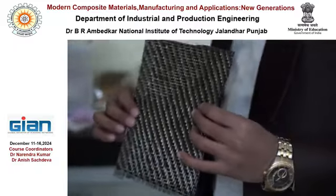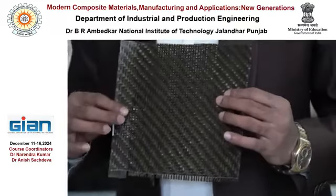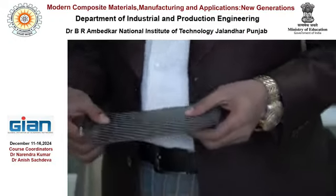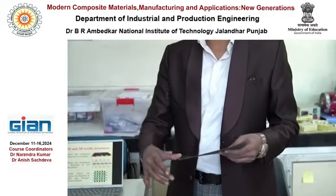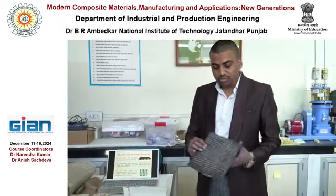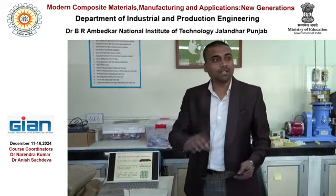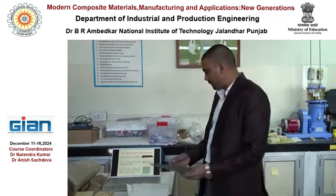In this particular case, we can see that the yarns are placed in two directions, and this fabric is two-dimensional. It has length and width dimensions only, and the thickness dimension is very minimal, so we do not consider it, and we say that this is a two-dimensional structure. We can also have the unidirectional preform, where the majority of the yarns are in only one direction, so that is called a unidirectional preform.